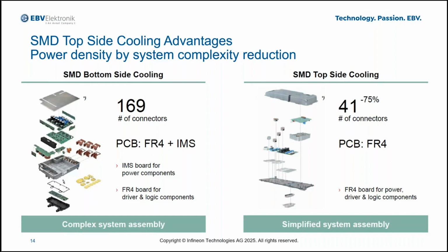Whereas at device and component level, there is not a huge difference in price between SMD bottom side cooling and SMD top side cooling. And with the increasing diffusion of these top side cooling devices, I am sure that the prices will also align with SMD bottom side cooling.